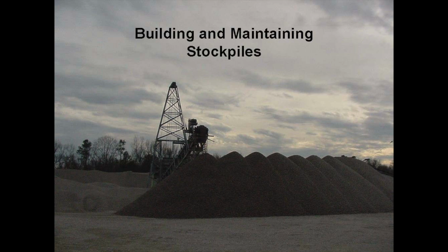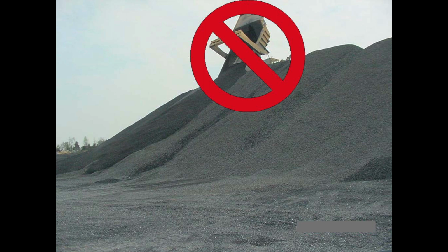What we're doing here is you can see that the fall is minimized, and the stockpile dumps are pretty close together, and that's going to help minimize segregation. A couple things with this slide. Number one, when you dump it over the front of the pile, it's just like that Thor stacker. It's all flowing right over the front. The other thing is that's pretty dangerous to do, right? Because all that weight's going up in the air at the edge of that stockpile. You can see that that's an open graded material, not a dense graded material. He could take a nice ride down that hill. You'd only do it one time.